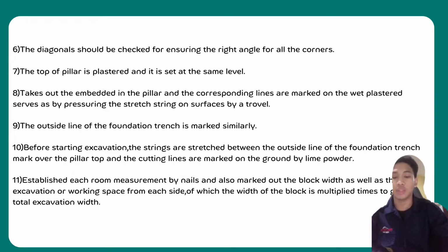Number 9 is the outside line of the foundation trench is marked similarly. Number 10 is before starting excavation, the strings are stretched between the outside lines of the foundation trench marked over the pillar top and the cutting lines are marked on the ground by lime powder.